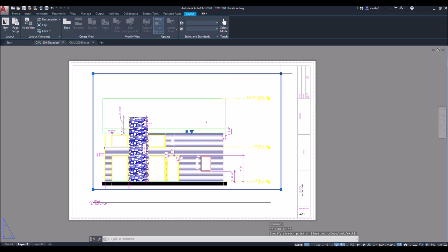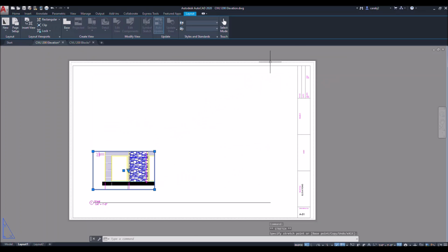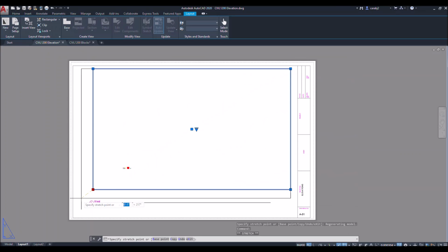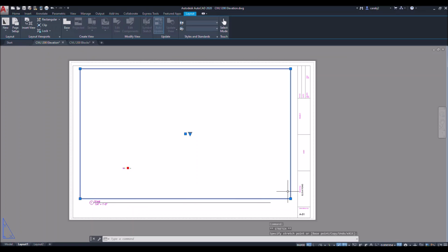So when you change your paper space page from 8.5 by 11 to an 11 by 17, it might show up like this, where the viewport window is super small, and then your model space images over here, or the drawings, are super small themselves, or they can be really big. Just make sure, don't freak out, it's not wrong. All you have to do is open up the window a little bit. You don't have to do it exactly, it doesn't matter.